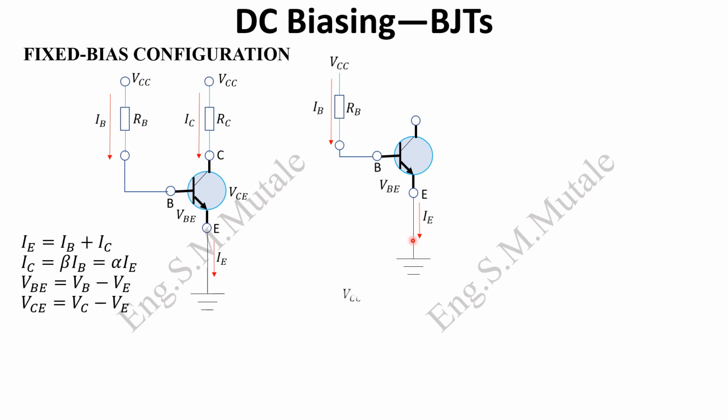So from here, let's derive an equation. You realize that we have VCC, which is the exciter. As it goes to the ground, it's going to drop. There will be a voltage drop there, which is the product of that current and that resistor, and then there is another voltage there, VBE, which is 0.7. Taking this route, you are going to derive that equation. You don't need to memorize this. Just know which route to take, and then you can easily come up with that equation.